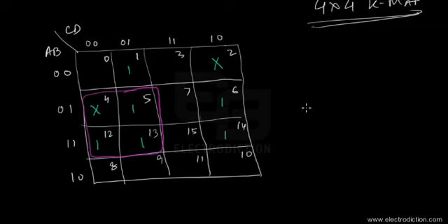If you see that including a don't care element helps in creating more groups together, only then are you going to use them to group up with the other elements concerned. These don't care elements are just present as a byproduct. They are certain elements that don't affect the system operation even if they occur in the function. So it's not a necessity to use the don't care elements if you don't require them to reduce the function.